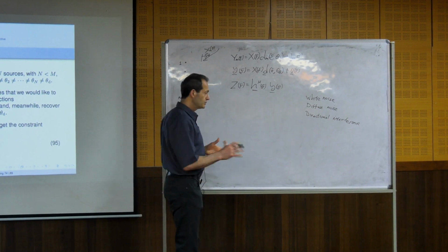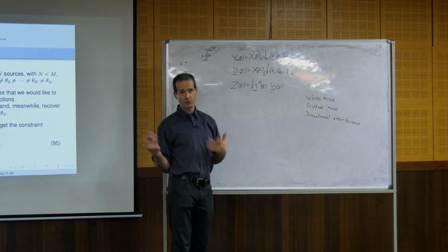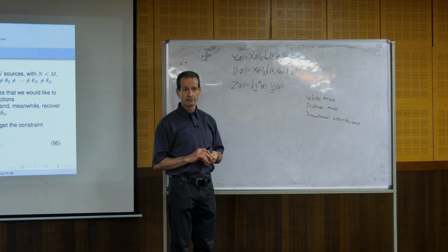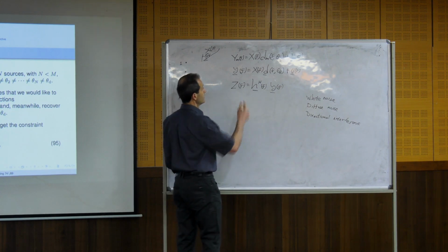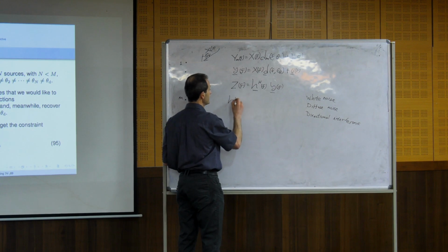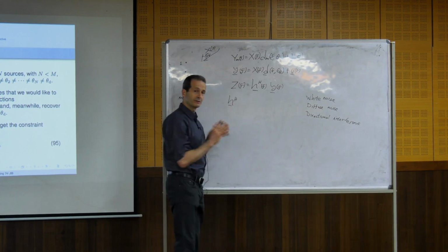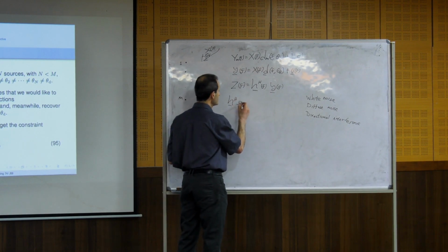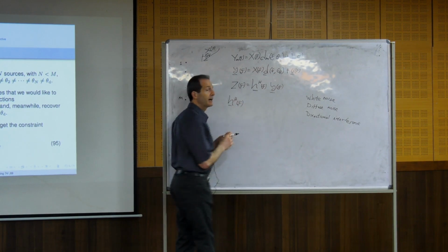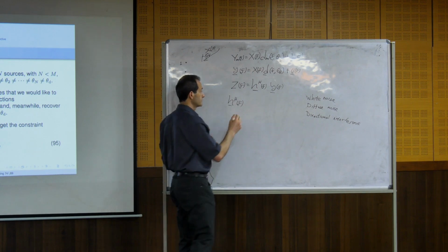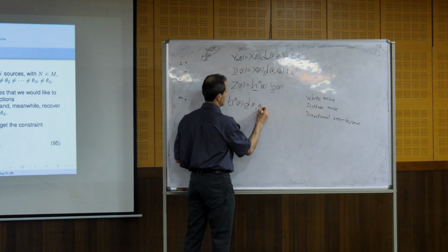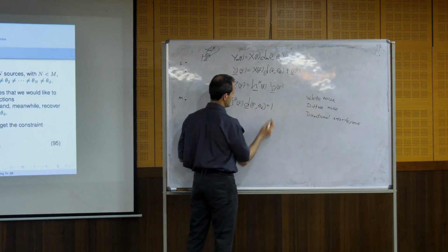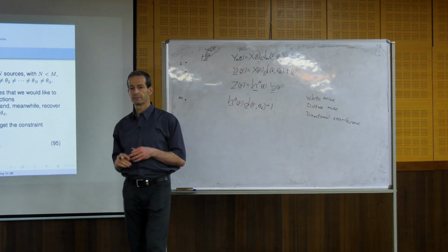So for all beamforming methods, we assume that we know the direction of the desired source, or we estimate it, okay? And then we apply a constraint that any beamformer that we design will not distort the signal that comes from theta d, from a certain direction. Okay, so it's one, and it's independent of the frequency.